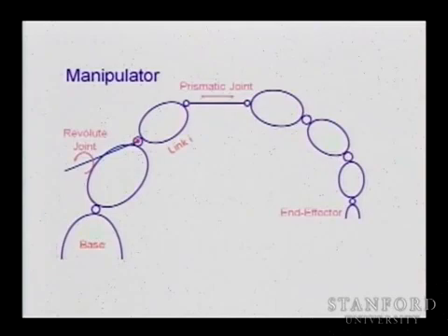So a manipulator is defined by a set of links connected through joints. The first of those links is fixed. We call it the base. And the last one is actually this gripper. The whole purpose of the manipulator is really to move this gripper and place it in space to do manipulation. Obviously, later we will see that it is possible to use the body, the links themselves, to do manipulation. We call it whole body manipulation. But for now, we are really interested in locating this end effector, at the same time locating any other links that is moving.